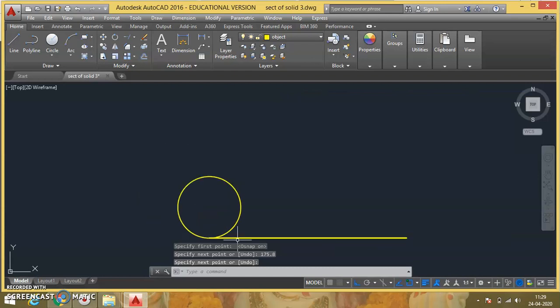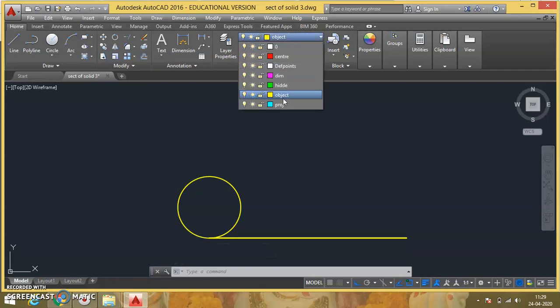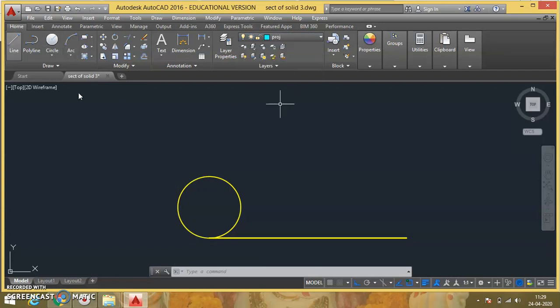Now the next thing I'll do is divide this circle into 8 equal parts. To do that, I can draw these two lines, and we'll draw a 45-degree line here and a 45-degree line here. Like this you resolve it into equal parts. Since we have considered 8 equal parts, each angle you get here will be 45 degrees.